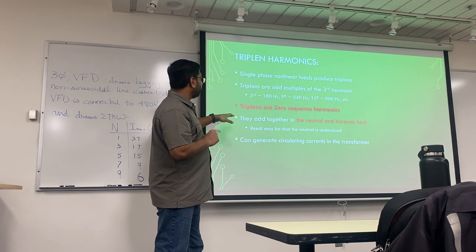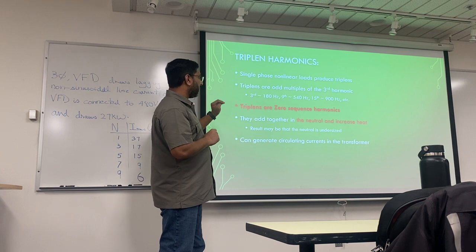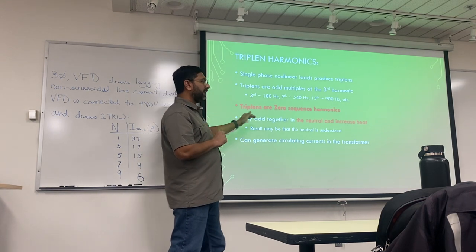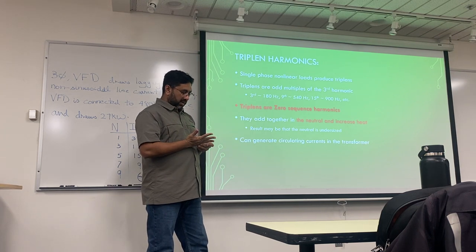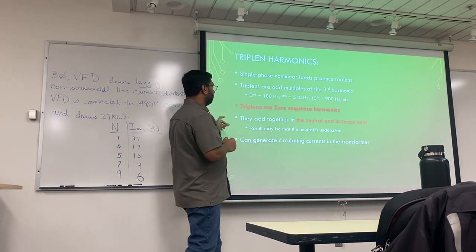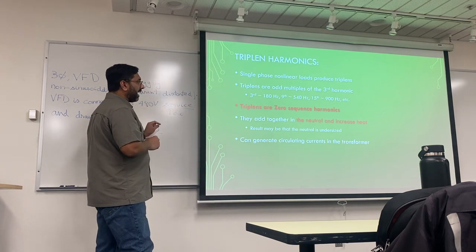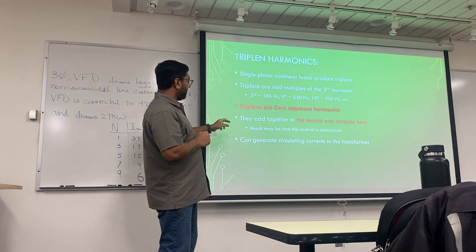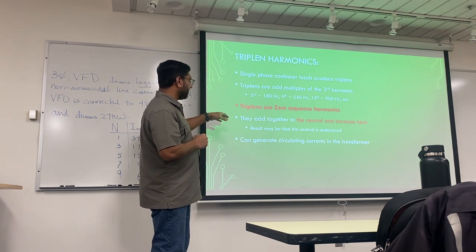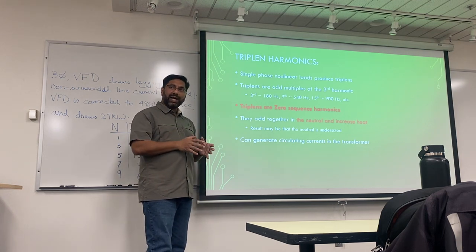So triplets add up in the neutral, and what happens is, if currents are adding up in the neutral, we began with a three-phase source and a load, and I showed you it's not necessary that you have a neutral, but always push your customers to have a neutral. And the reason is because of these harmonics.